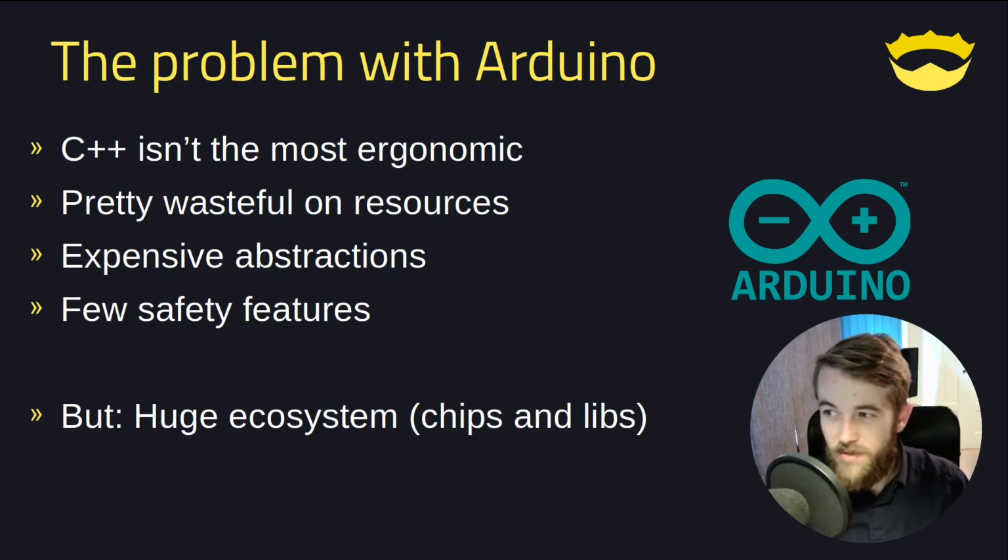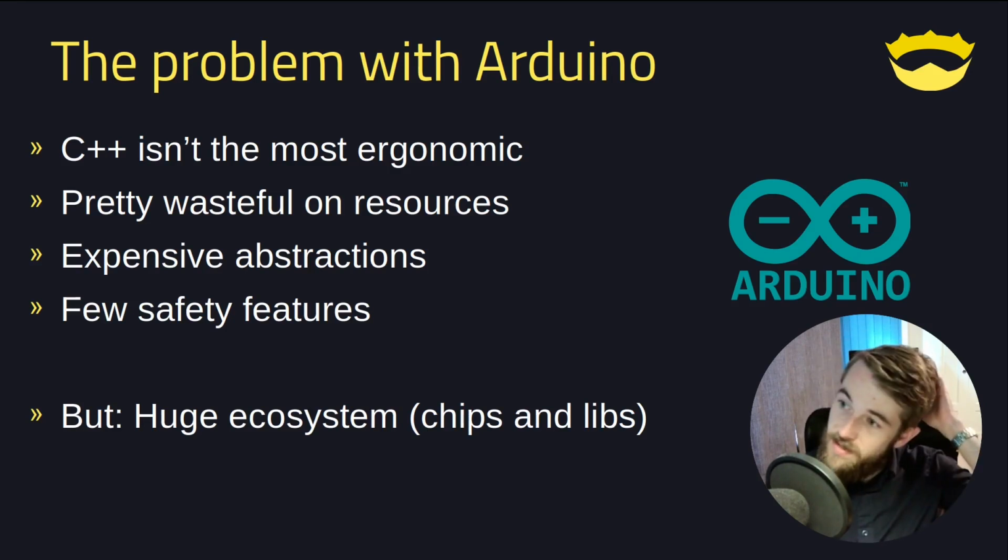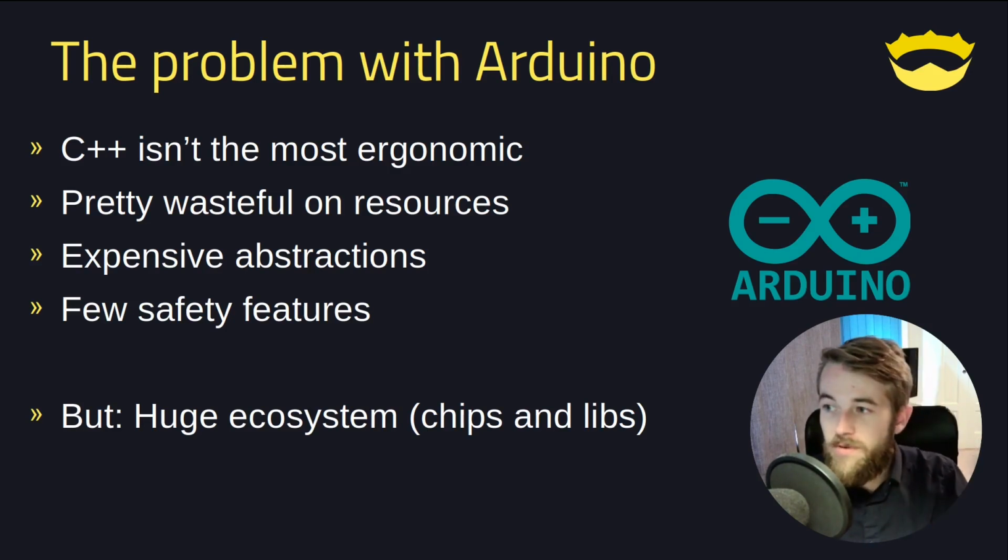Program memory is a bit special. You can think of it sort of as a file on the Arduino system. It's just stored along with the code instead of stored in memory, like data would usually be. And all of these sprites are just a pointer to some data in program memory.